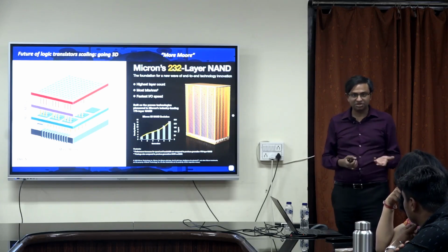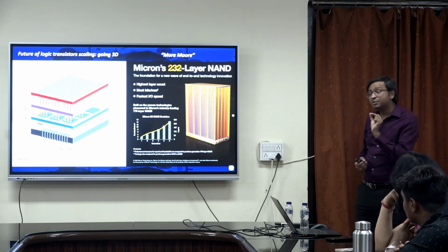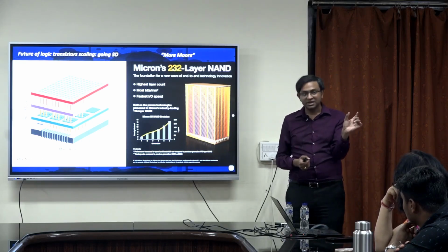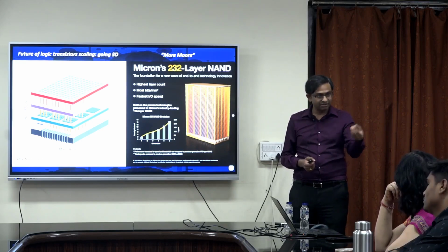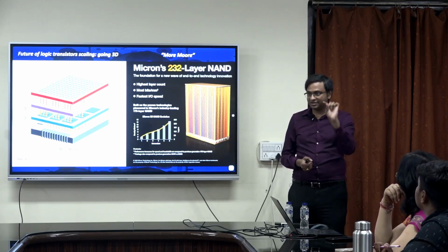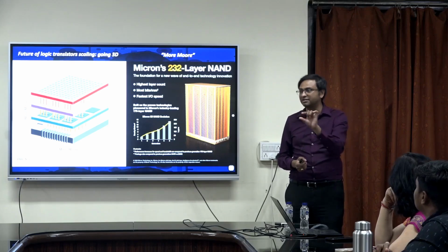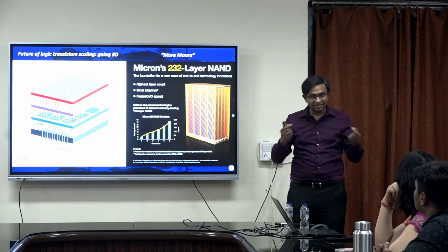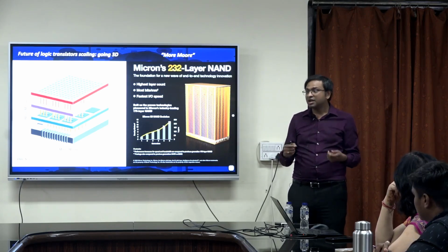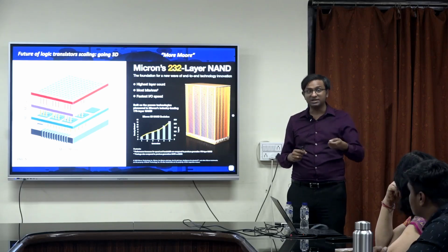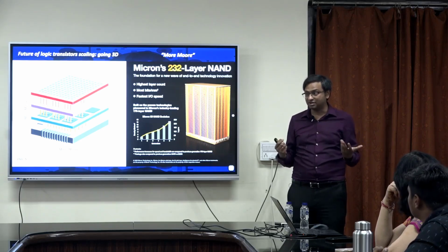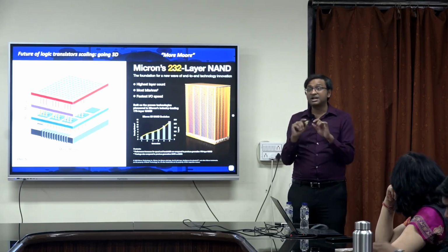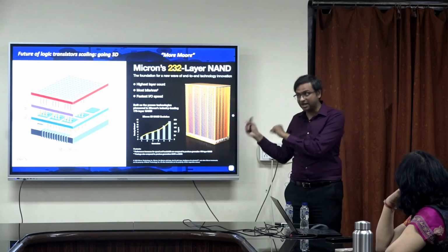You can say, okay, memory is also transistors, right, but memory transistors don't have to be high performance. What does the silicon channel do there? It is just for a readout. Remember, in a memory device, it was a readout, and the storage was mostly in the oxide, the dielectric, right. So, there I do not need really very high quality silicon channel. What I could do is simply do a very quick pulse of high temperature, called rapid thermal annealing, and I get a decent quality polycrystalline silicon, not like a single crystal silicon channel, which is required for high performance.